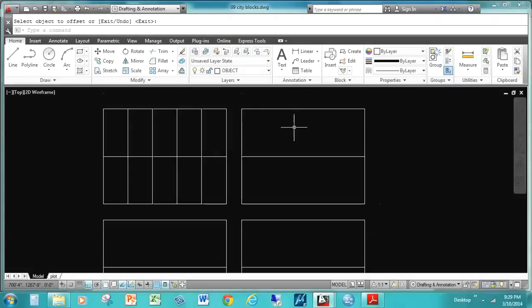This time we can use the offset command, but then we have to maybe trim off the first line, and then we can copy it or offset it. Let's practice using the divide command for this part. Before dividing this line, we should change the point style. Otherwise, the points appear as dots and the line covers the dots, so we won't be able to see the dots. In order to change the point style, let's type in PD mode, enter, and